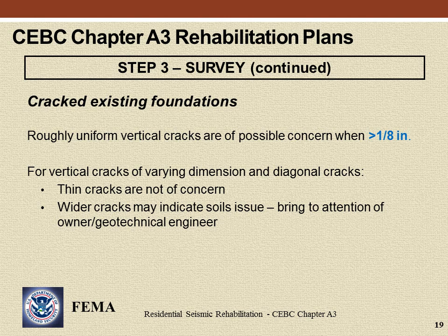Significant vertical or horizontal offsets to either side of a foundation crack are one indication that foundation movement might be significant. In that case, evaluation by a geotechnical or soils engineer is recommended.